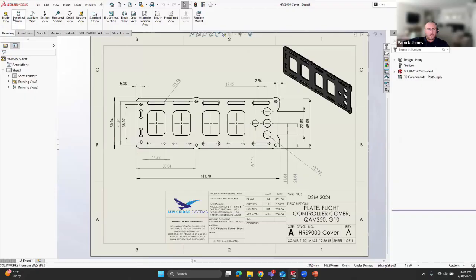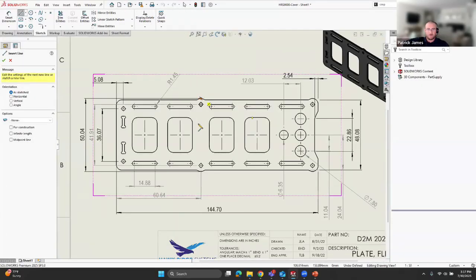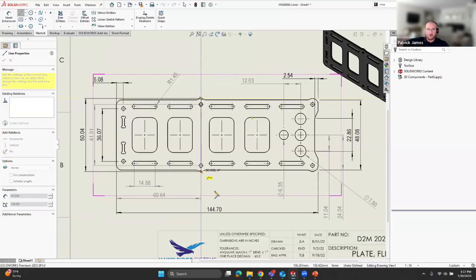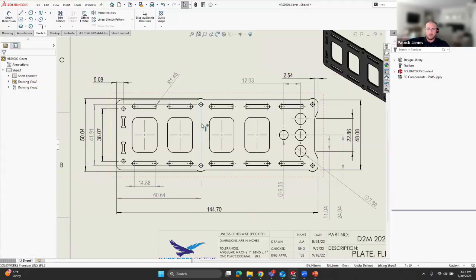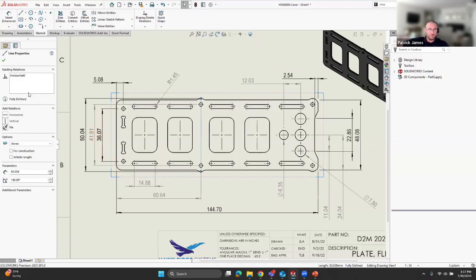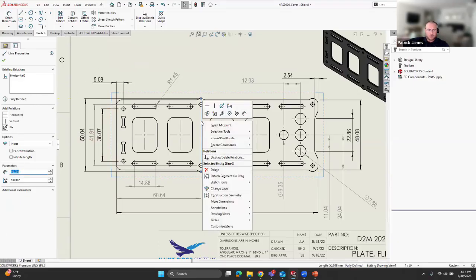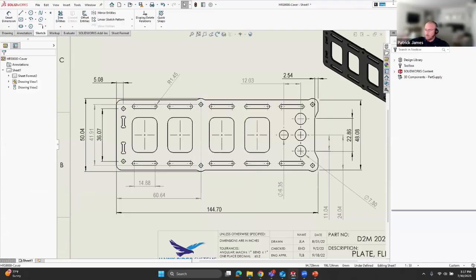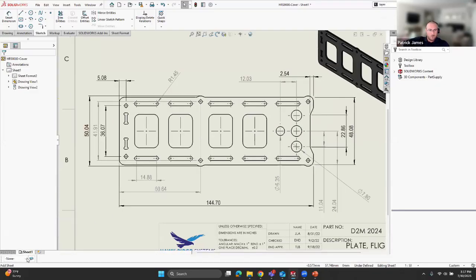Oh, good. I do have a drawing for this. So I guess we can do this with any line. Just changing the format of it would be the quick and dirty way. You can do a section view too and tell the line style to be whatever you want. But in here, I probably just want to pick the layer of the line. If we're doing it manually, choose my layer and then just change what my line format looks like. Here, I'll pull up my layers toolbar.